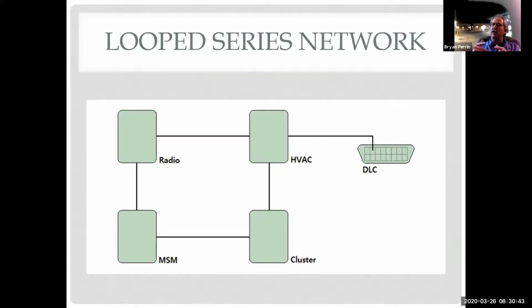So in other words, in network, which is very different than when we're working on powertrain management or transmissions, where we go to that module and we look at what are the problems that that module sees? With network faults, we look at everybody else in the room and say, who messed up? Because if all the other modules are saying, hey, I tried to talk to the cluster module and cluster module didn't answer, but yet when cluster module comes back to work and I ask cluster module, is there a problem?